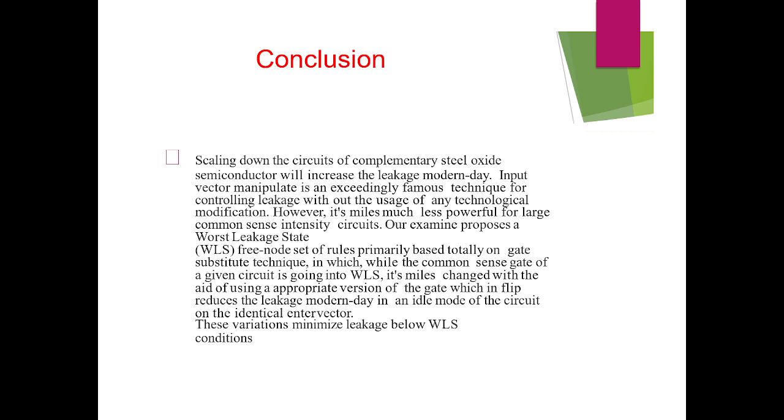In conclusion, I'd like to say that scaling down complementary metal oxide semiconductor circuits increases the leakage current. Input vector control is an extremely popular technique for controlling leakage without any technological modification, however it is less effective for circuits with large logic depth. Our study proposes a worst leakage gate, WS, free node algorithm based on a gate replacement technique, in which when a logic gate of a given circuit goes into the WS, it is replaced by an appropriate version of the gate, which in turn reduces the leakage current in standby mode of the circuit for the same input vector.